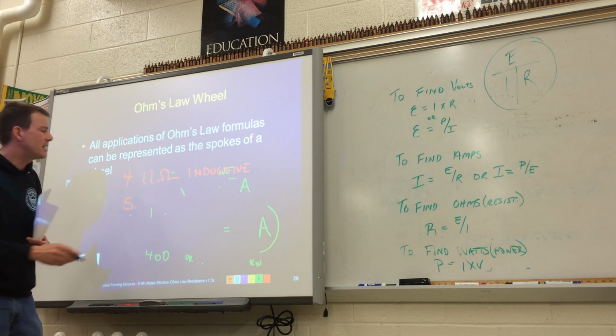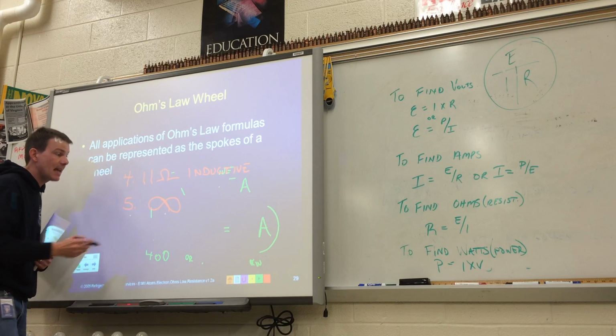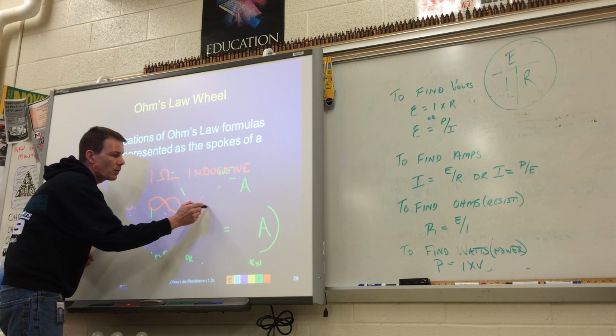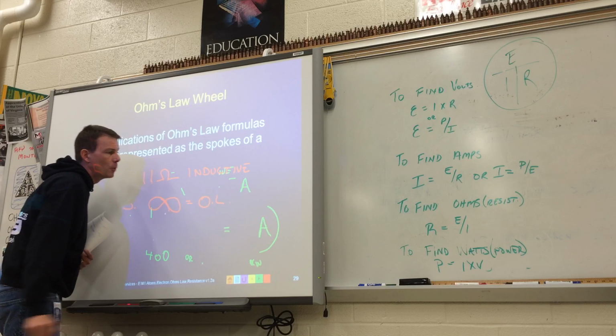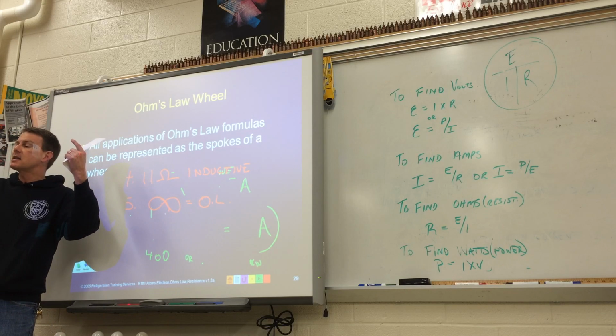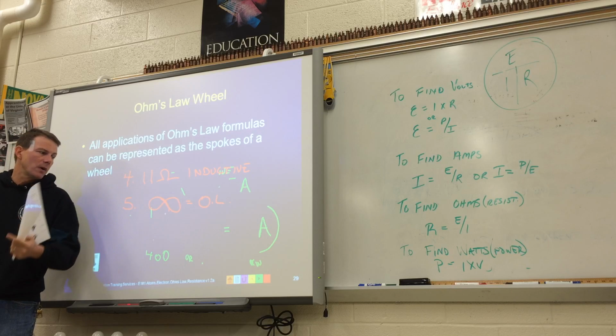The meter should have never said nothing but open link, or an infinity reading. Anybody ever seen that crazy 8 symbol before? Yeah. That is the same thing as what we have on our meters now. It's OL. Open link. It means it's never making contact. That contact is like the switch being off. Switch was off, contact wasn't closed, so that meter should have just read OL, open link, all the way through it.